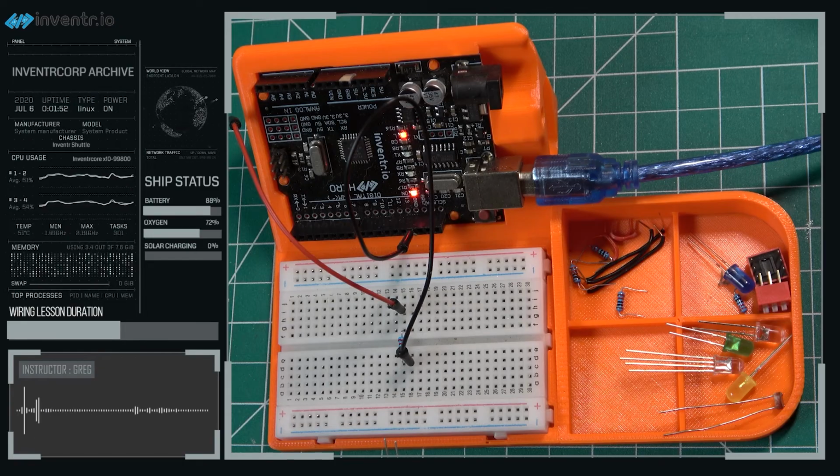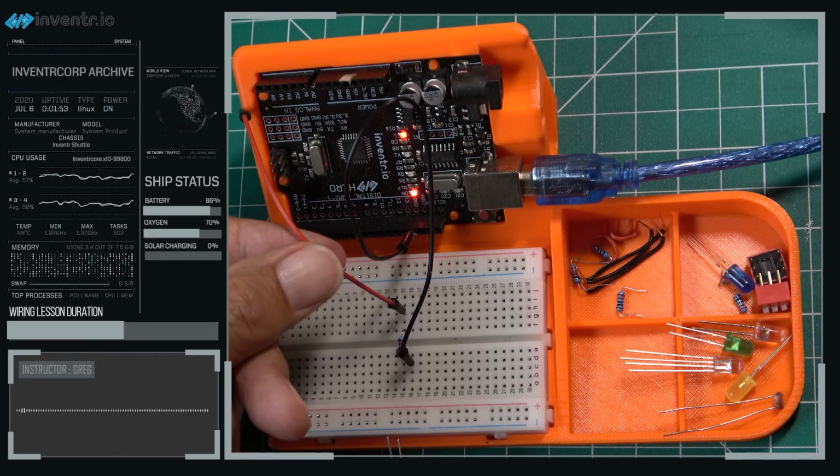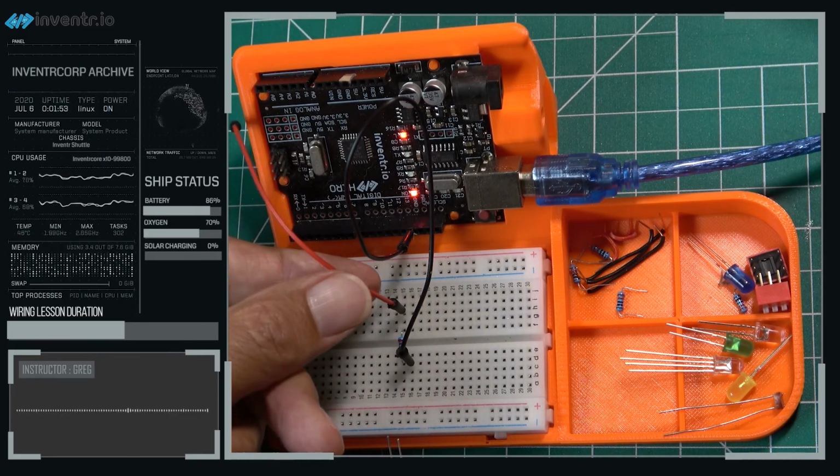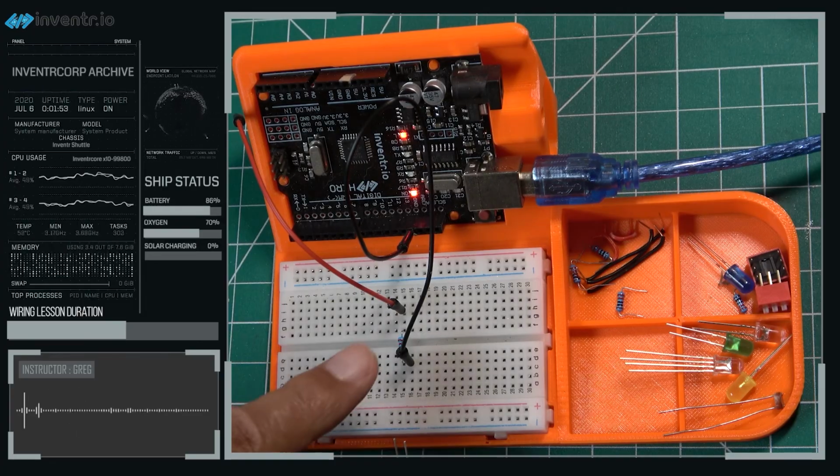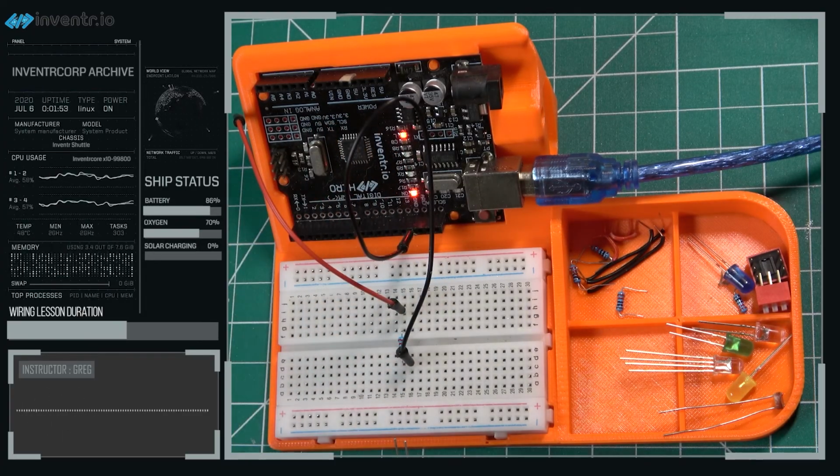At this point, we are ready to assemble our circuit, and we will be using a very important convention throughout our projects, and that is we'll use a red wire here to denote the fixed high or 5-volt supply, and we'll use a black wire here to denote the 0 volts or ground connection of our circuit.